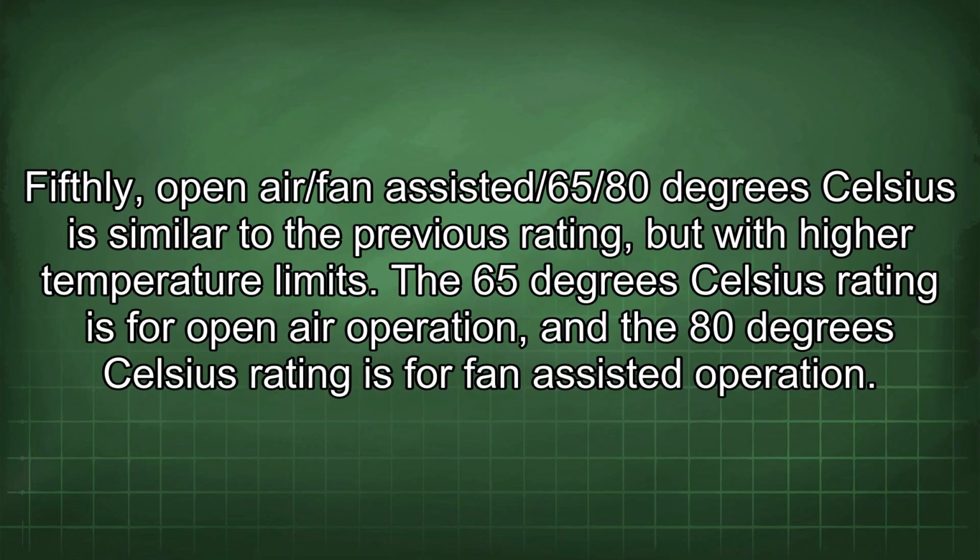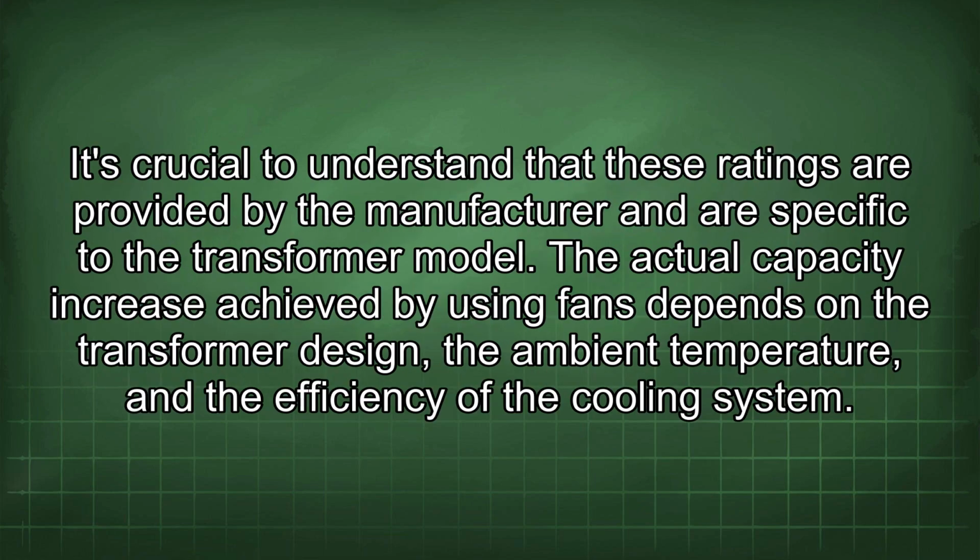Fifthly, open-air/fan-assisted/65/80 degrees Celsius is similar to the previous rating, but with a higher temperature limit. The 65 degrees Celsius rating is for open-air operation, and the 80 degrees Celsius rating is for fan-assisted operation. It's crucial to understand that these ratings are provided by the manufacturer and are specific to the transformer model. The actual capacity increase achieved by using fans depends on the transformer design, the ambient temperature, and the efficiency of